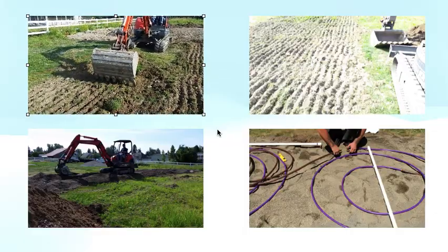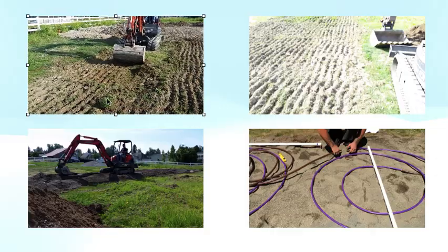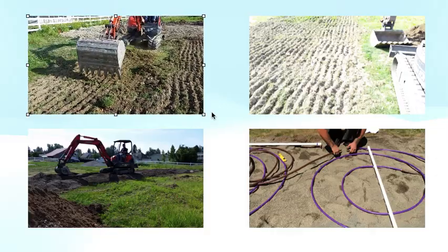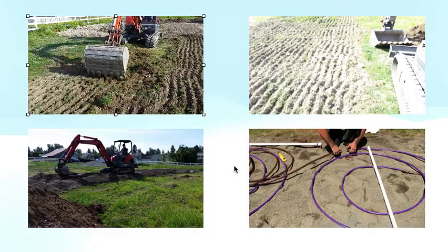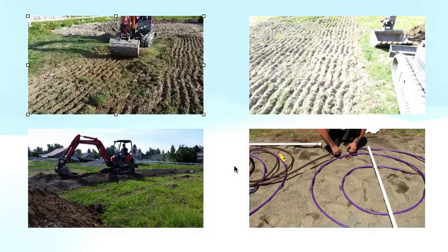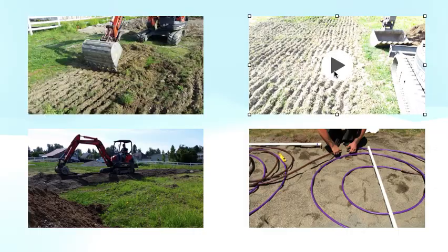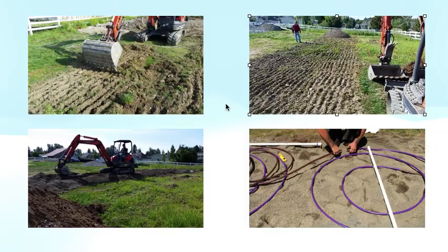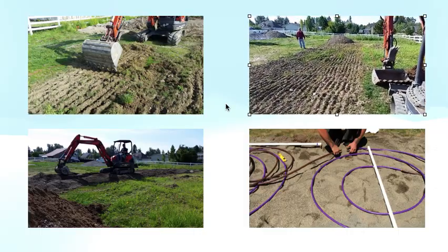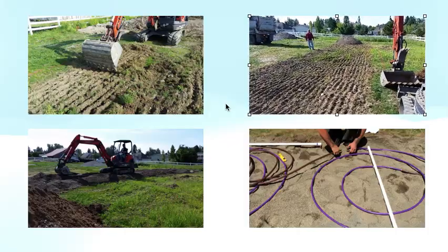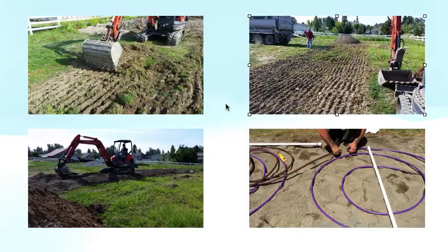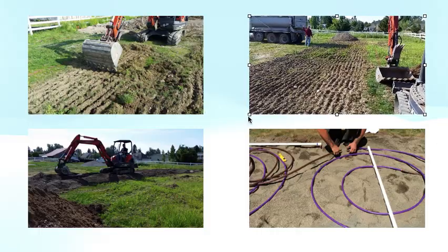You'll see plenty of clumps of sod that are left or have been moved around. That's fine. Leave them as they are. But we just want to comb through that designated basal area. And that's what we're looking at there. After that, once you've done that, we're going to apply this sand. And so you'll see shortly a truck back up, and from the side, it's dumping sand onto the prepped soil.